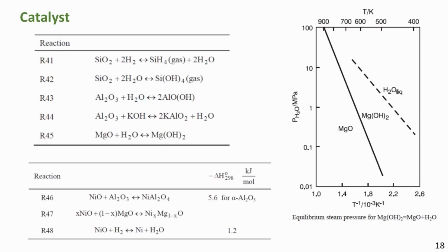The industrial catalyst is supposed to serve conditions in tubular reforming involving steam partial pressure close to 30 bar and temperature at the reactor wall above 800 degrees. The support should be able to withstand these conditions without losing strength. Furthermore, it should not contain volatile components. Some of the support reactions are listed in the table.